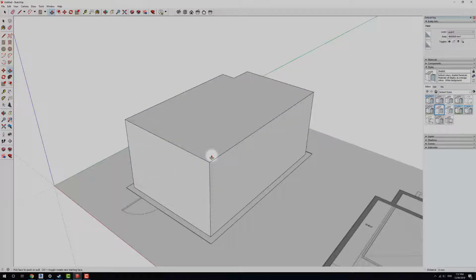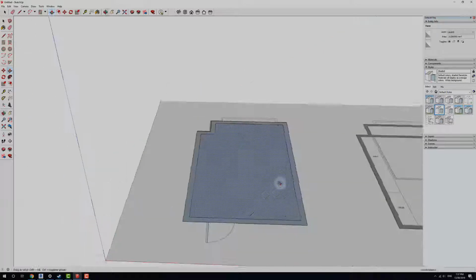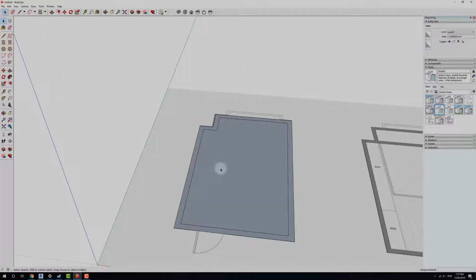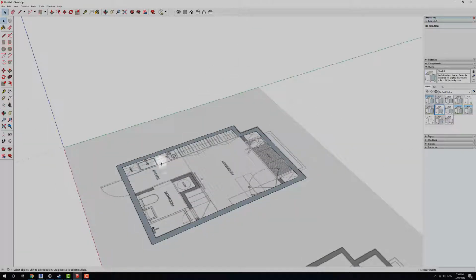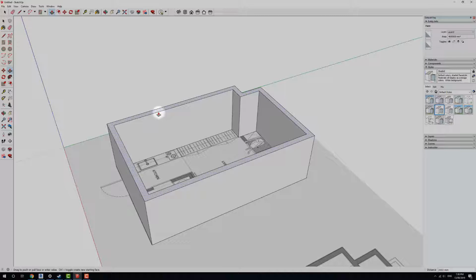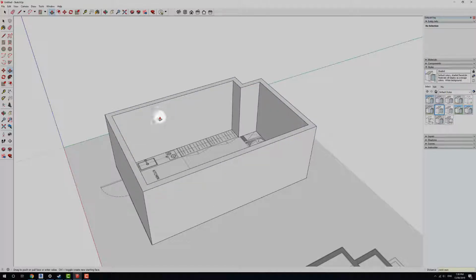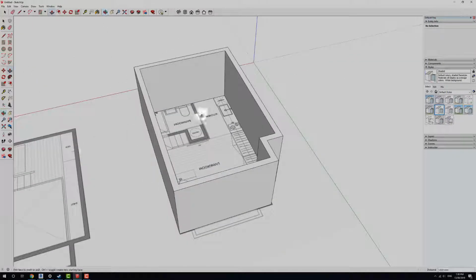Now I'm going to Control Z both of those, and bring it back down into here. I'm going to delete this middle portion by selecting once to the face and just hit delete, and you notice now I've just got my walls. So I can click on this, drag it up, and here I can type in 2400, standard wall height, sorry.